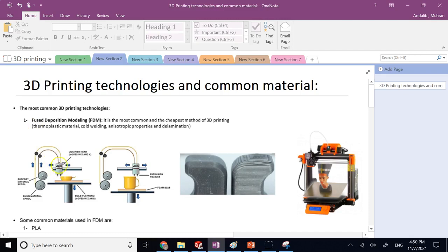In the extruder, this motor pulls in the spool through a gear mechanism and brings it to the hot end, where the heating element brings that plastic almost near the melting temperature, a little bit below that. Then this almost molten plastic, which is highly deformable, is deposited on the print bed for the first layer and then on top of the previous layers for the other layers.